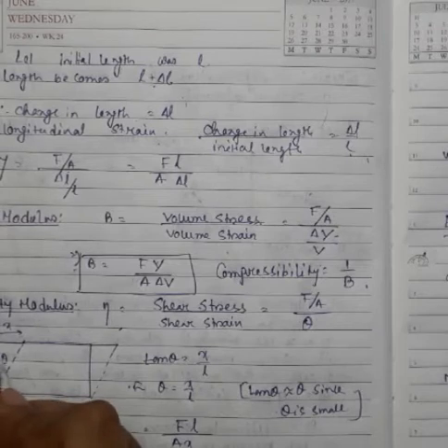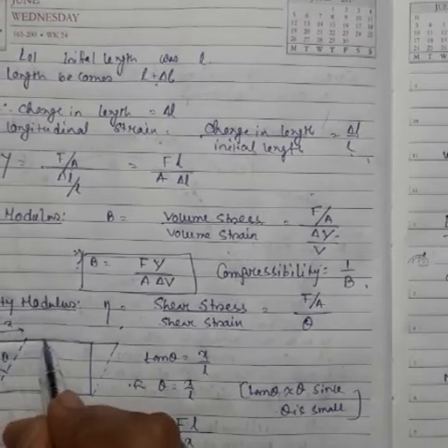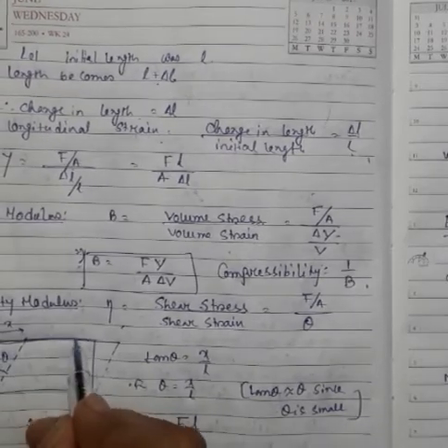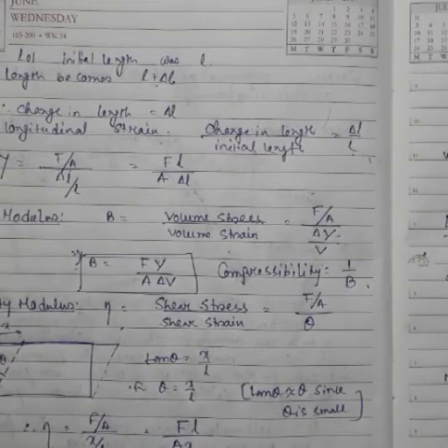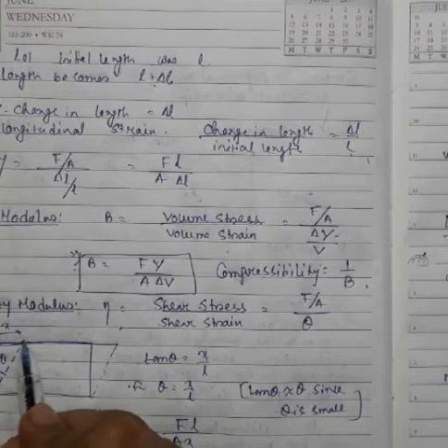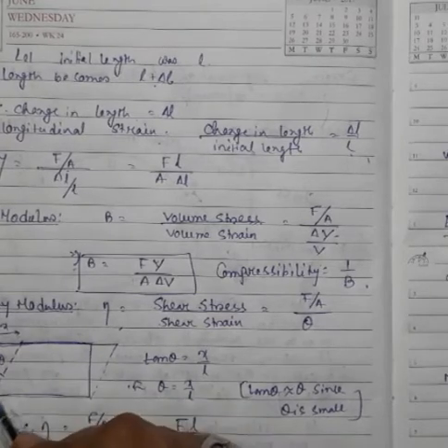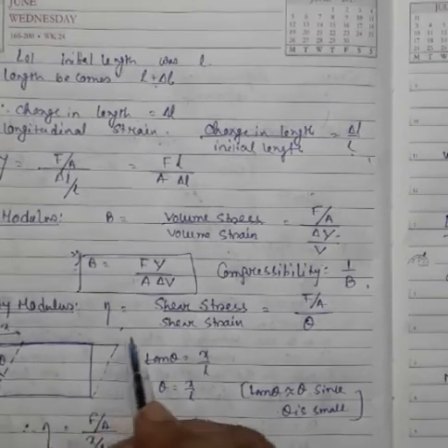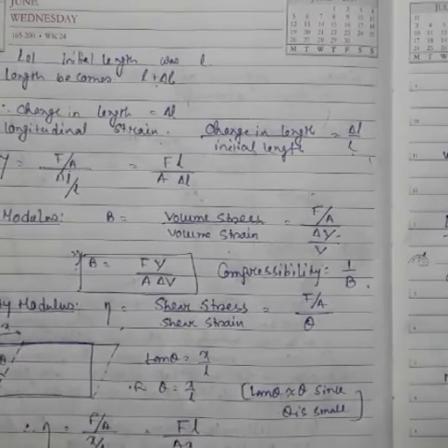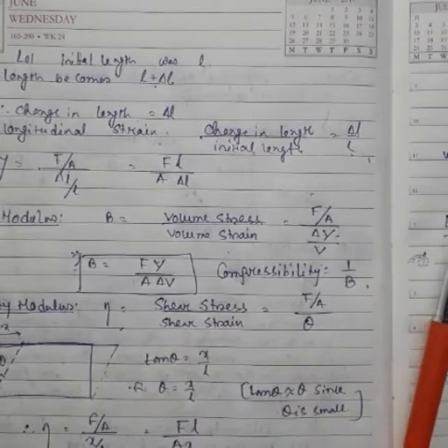You can imagine this is shear stress, since this force is tangential to this surface, and this force is acting on the upper surface. The force is tangential to the upper surface, so that's why this stress is shear stress. That will move the upper surface in its direction, keeping the lower surface fixed. So that will produce a deformation, a change in shape rather than size. This is how shear stress works. Now rigidity modulus is all about the changing of shape.